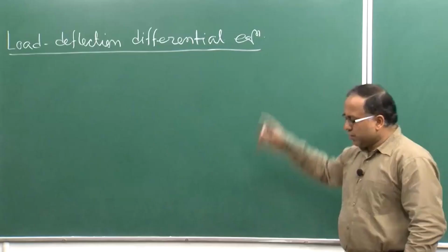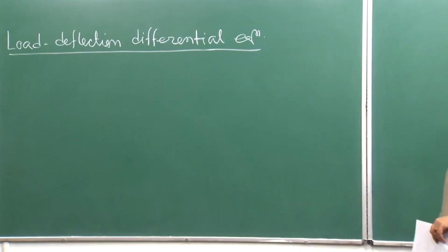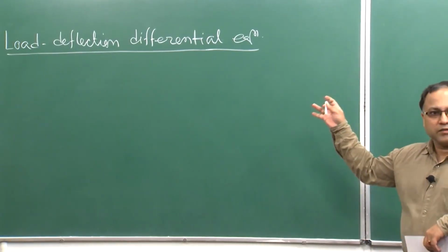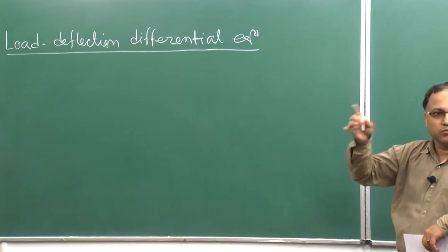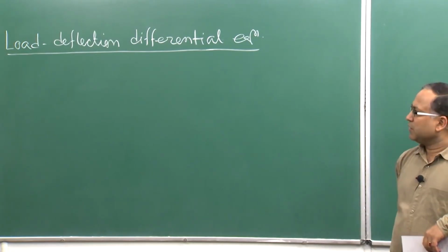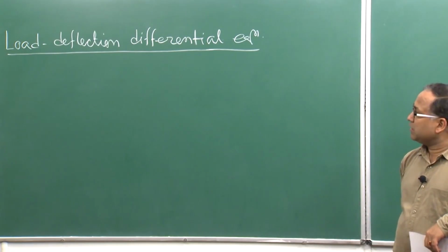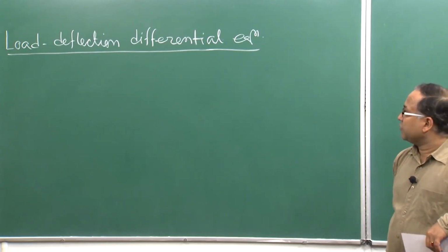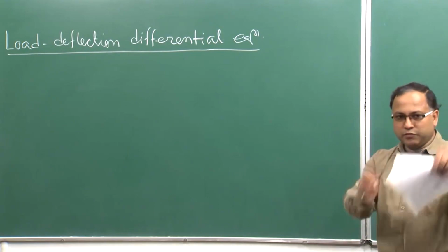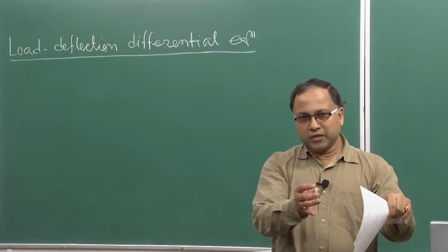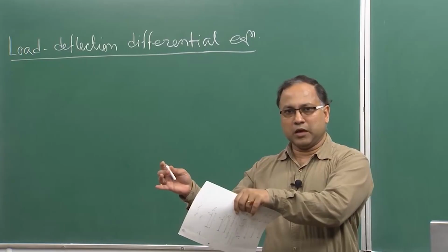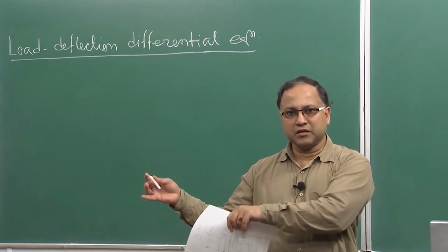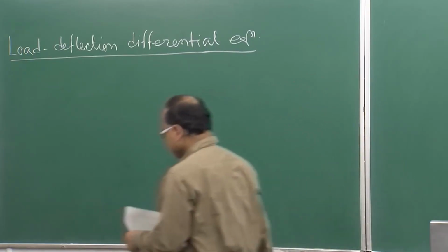So, today we will be talking about the load-deflection differential equation. From the bending moment and deflection relation that we established, we can derive this load-deflection differential equation. That means if you know the load, this differential equation will give you the deflection. So, let us establish that.